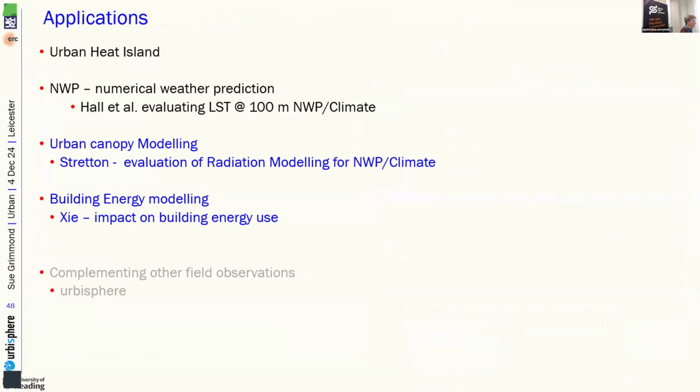Yes, you will see that, and if you go back to that video, you will actually see the rate that it's cooling. So the roofs will cool and become isothermal faster than the walls because they see more of the sky. But straight after sunset, there will be strong contrast, and then just before sunrise, the spatial variation will be least. But yes, there will still be large variations at night.